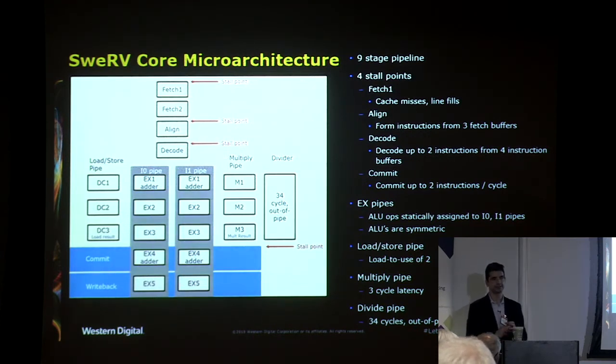That's another sort of tribal experience from the industry. When you get a load that misses and needs to go to the slower flash on the platform, this is a larger number of cycles, potentially, I'm not supposed to say, but say much larger than 2. Guys, this is normal. You put in some flash and you don't want to spend a ton of money because this doesn't happen often, so you optimize it for size and not for latency.